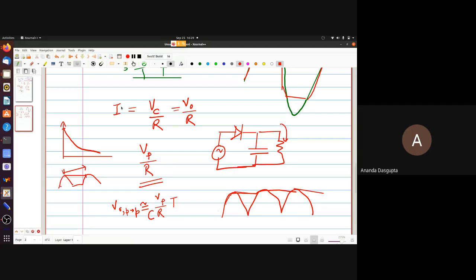So you will have to take the fact that the shape is not really a straight line, it's an exponential curve, so you have to estimate the RMS value for that. It's not really a triangular waveform, but a curved wave. You also have to take into account that the input voltage picks up and the diode forward biases before capital T time is reached.